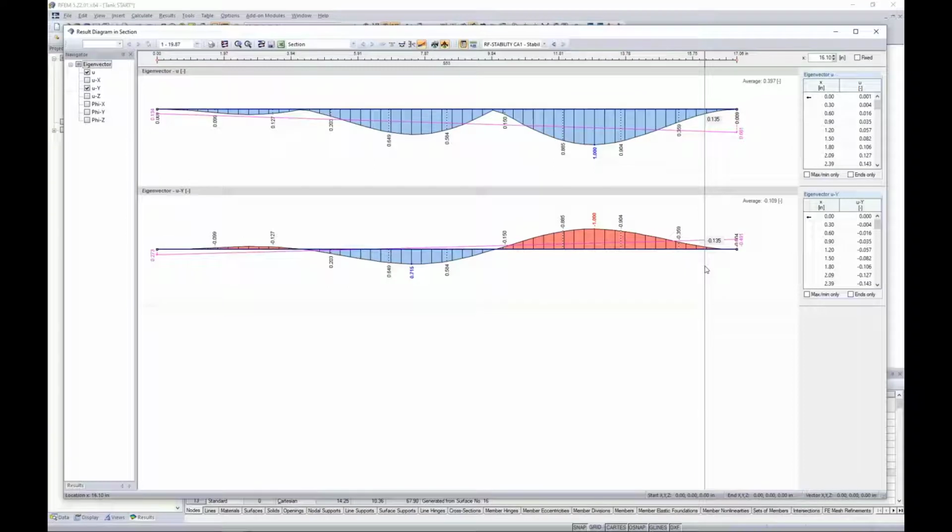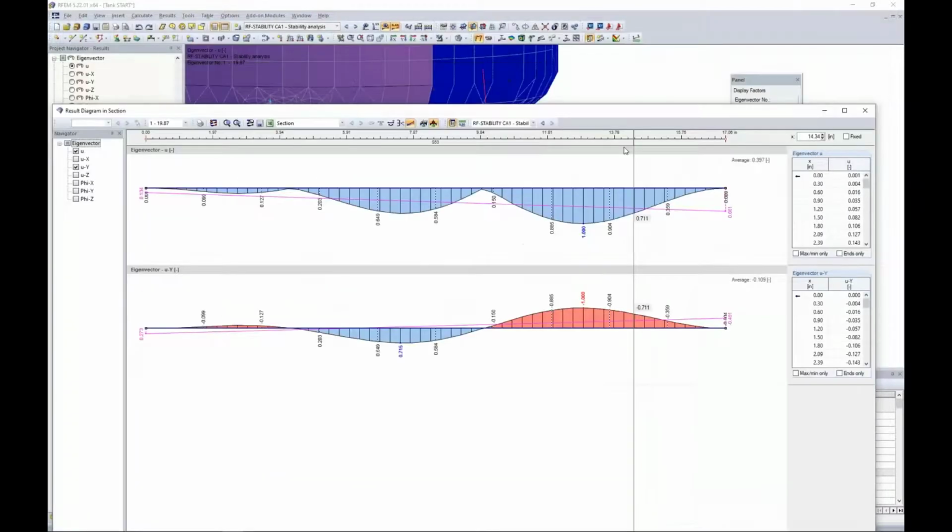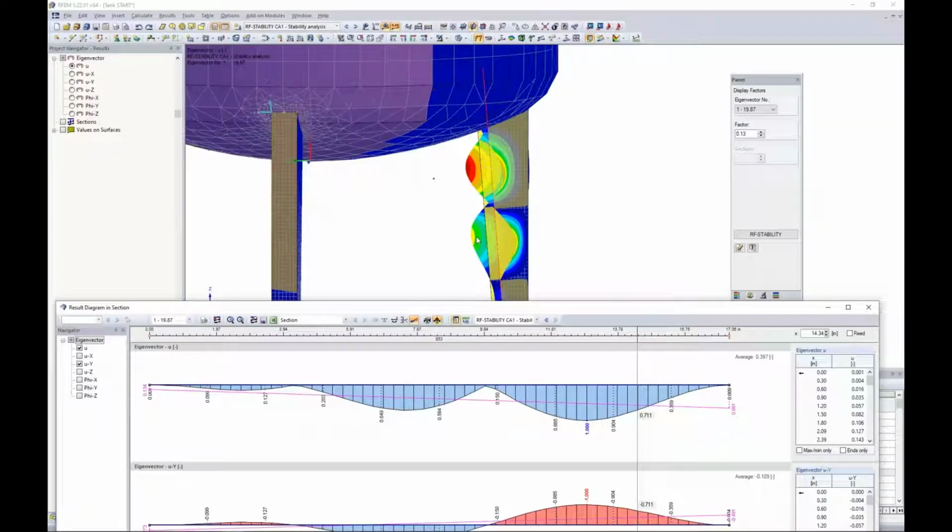Now, the reason that I'm doing this whole procedure is because I want to relate this buckling to modeling imperfections. And we all know that when we are constructing a tank or any type of structure, there are installation errors, maybe there's incorrect construction methods, or we don't properly manufacture the elements, and inevitably we have imperfections. And everything that we are modeling within the RFEM program here is perfect, essentially.